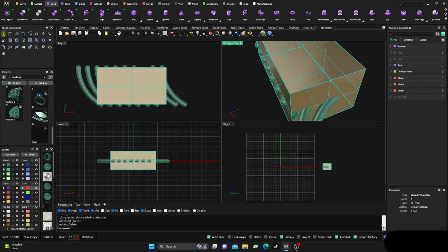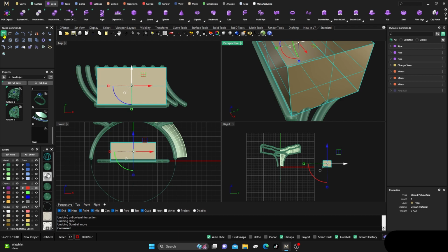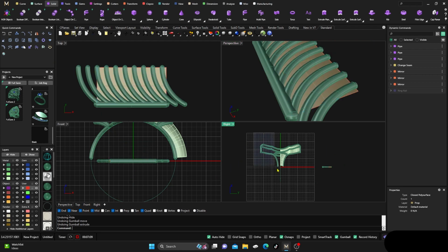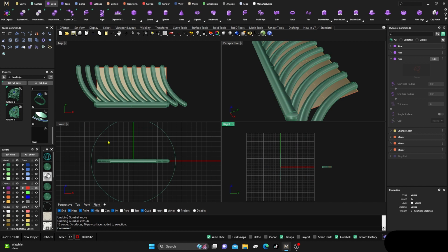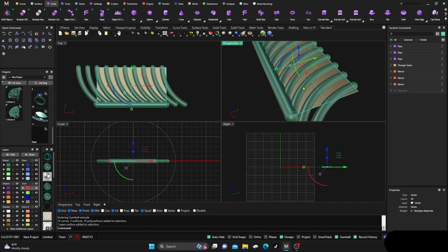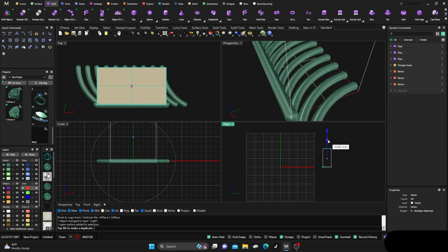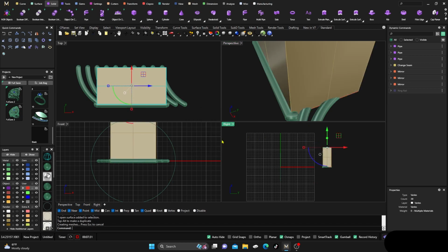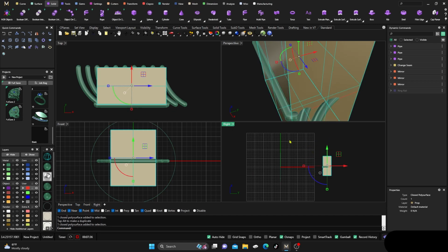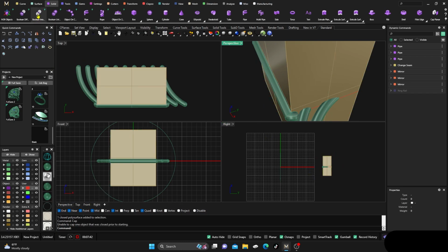So I'm going to go back here real quick before I did the extrusion. First of all, I'm going to select this and then hide it so it's out of the way, right? I want to duplicate this border. So I'm going to duplicate that surface in place, change it to this white layer and then turn it off for right now. Now I can select that surface, extrude it up. Broke history, no big deal. Click on it, bring it down, cap, enter, and then do that Boolean intersection.